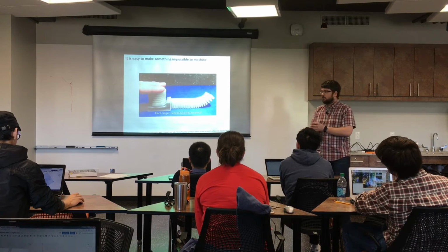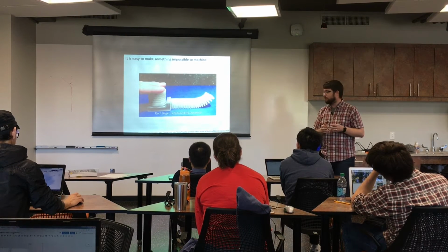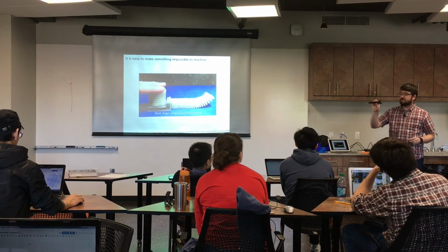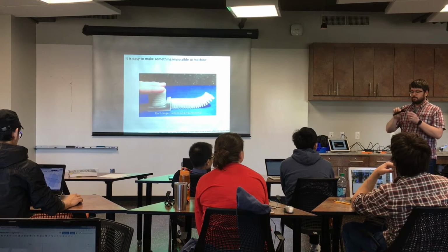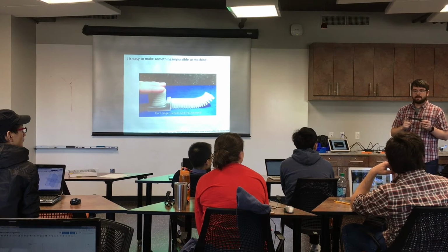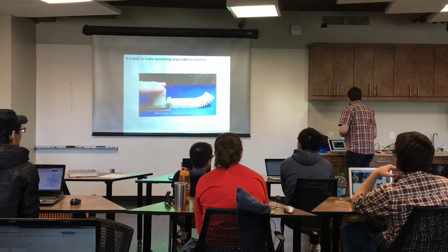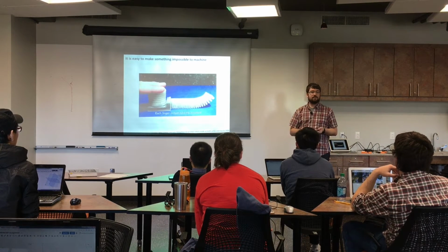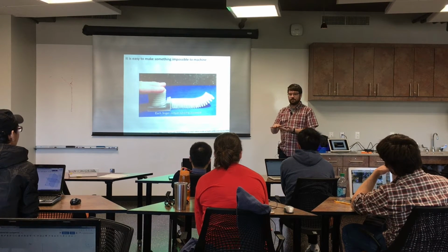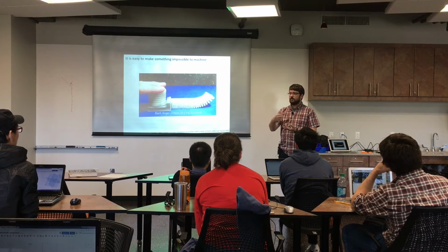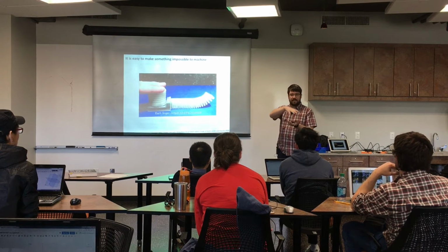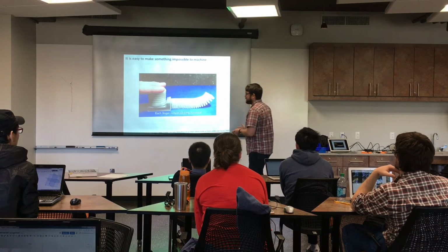You can also, if your end goal is to design something and you're 3D printing a prototype like this, or let's say we were designing a wrench and we wanted to eventually have this machined, we could design features into this that there's no way the machine shop or the foundry is going to be able to make, because we can do stuff like put passageways that have strange shapes and turn inside the part. There are even some people that have printed parts and then halfway through the print, they'll have a hole where we're going to put a nut or some other internal feature. They'll stop the print, put in the hardware, and start the print again and actually encase the part inside the print. So you can't really do that in the shop.